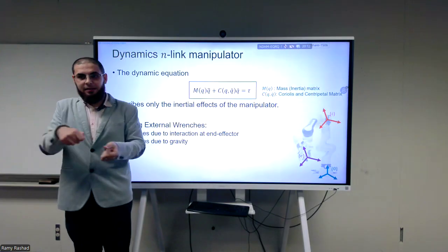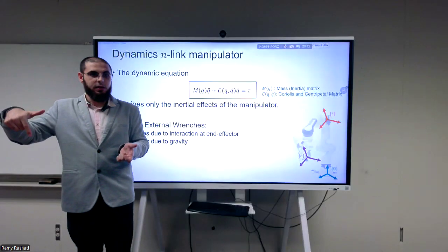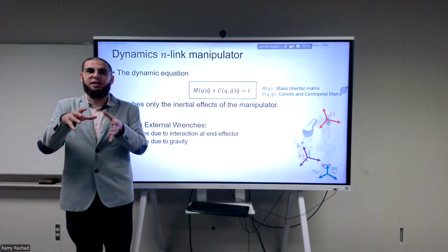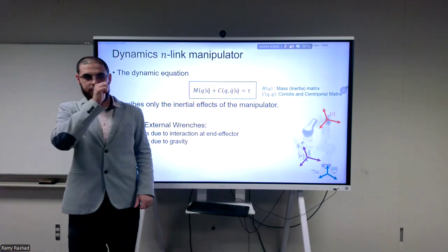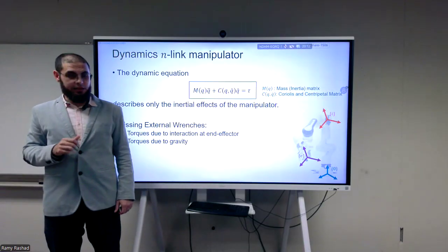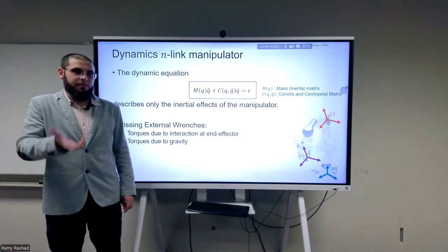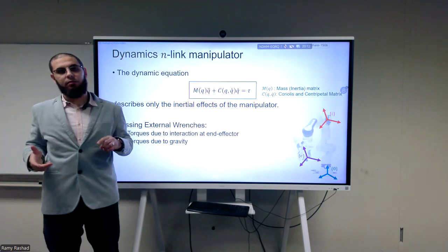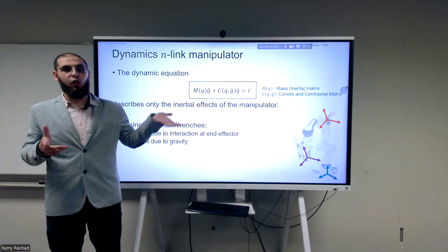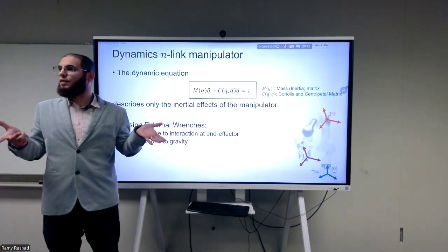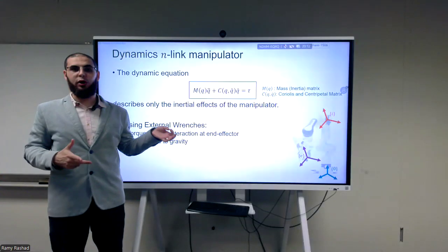Then, intermediately, you can add another frame at the center of mass, do the calculations there, and use that joint to transform all of the quantities from here to there. The gravity, we are doing it sort of offline, separately. That's right, and then putting it back into the algebra. Exactly. So you can put this intermediate frame at the center of mass and then transform. Or, easier, there is actually a formula, I'm going to show you now, that will give you the gravity wrench applied at any location, not just at the center of mass. So there is a much more elegant way to do it.